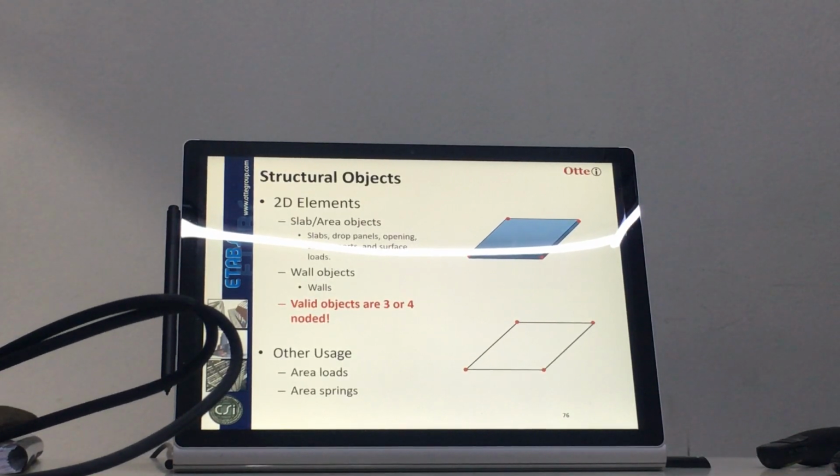The only problem we have is like an old professor. In the old days, Etabs meshing is not so powerful, right? So if you're not careful, after you apply the meshing technique that you apply, you may end up having some element with 5 sides. Because you say cut there based on this node and all stuff, and then some elements are 5 sides. So this 5-side element is called illegal element. When you analyze, it will disappear. You get thrown away. So suddenly after you analyze it, why I have a hole right there? So that is the reason why. Because you accidentally meshed the floor into a 5-sided element, which is illegal.